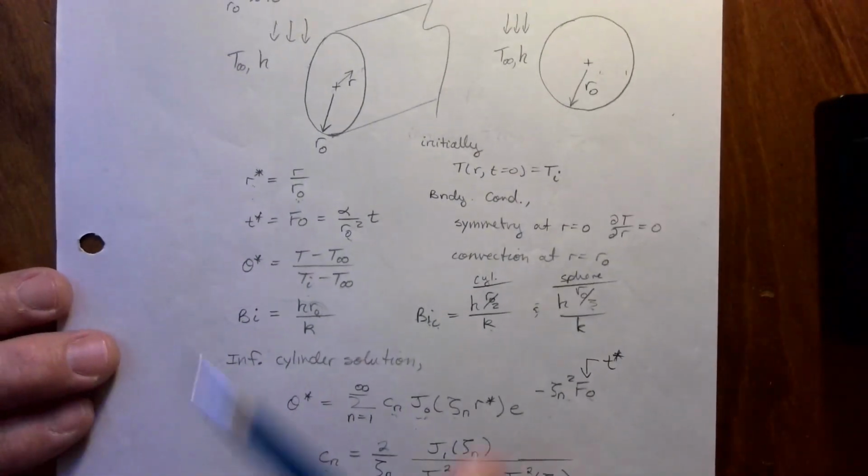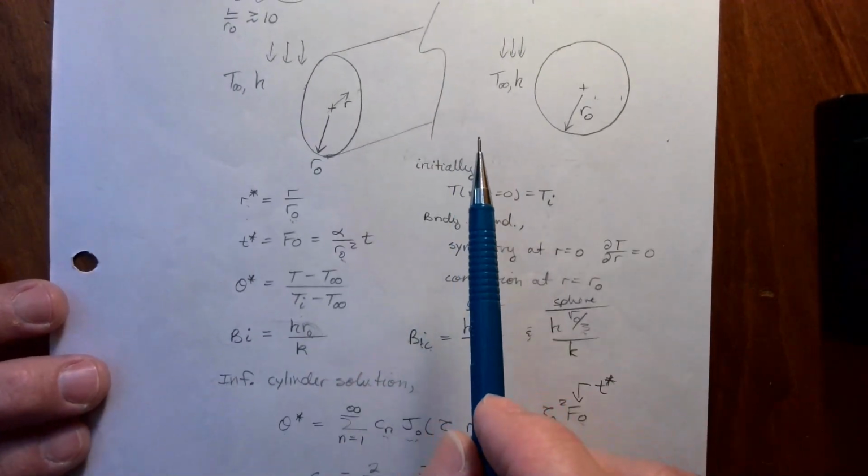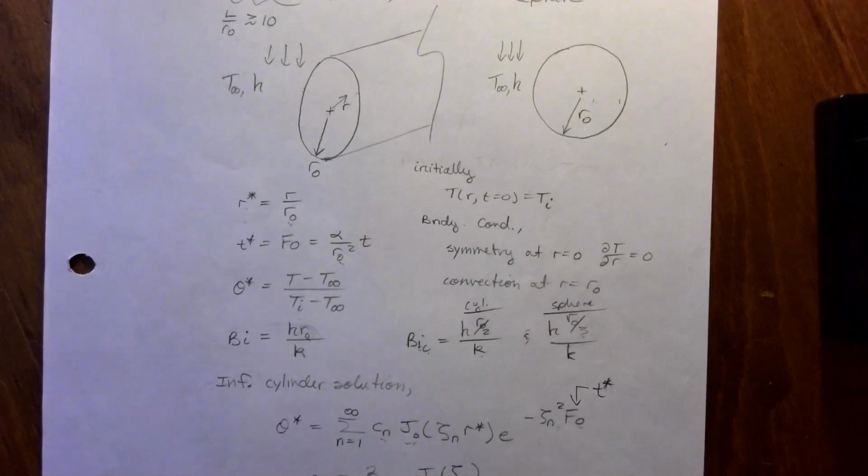The governing equation is actually different between these and also in comparison to a flat plate. We don't need to go into the details of the differences in the governing differential equation because we actually have a solution that's already been made available to us. It's a scaled solution, so we need to know what the scales are so that we can appropriately convert their dimensionless solution into our particular physical dimensional problem.